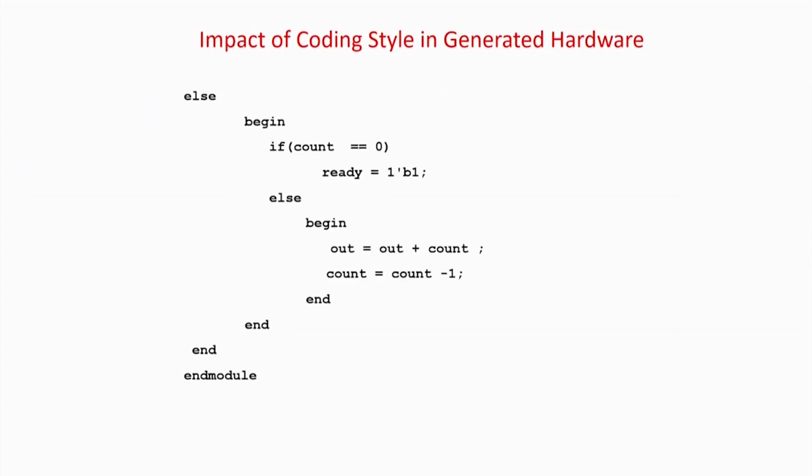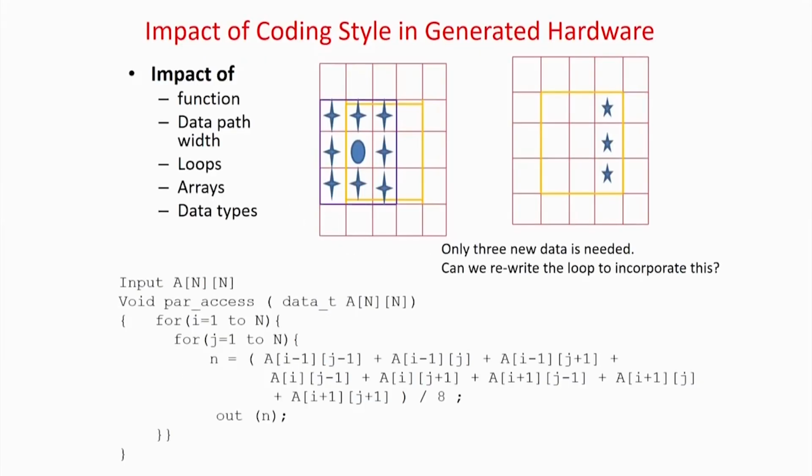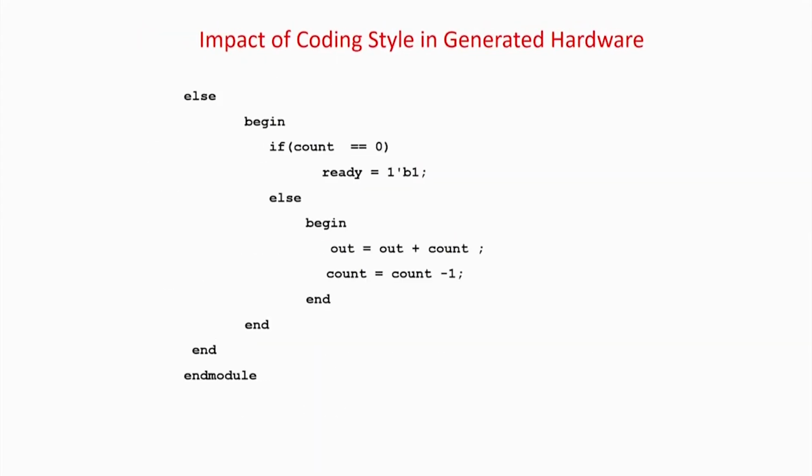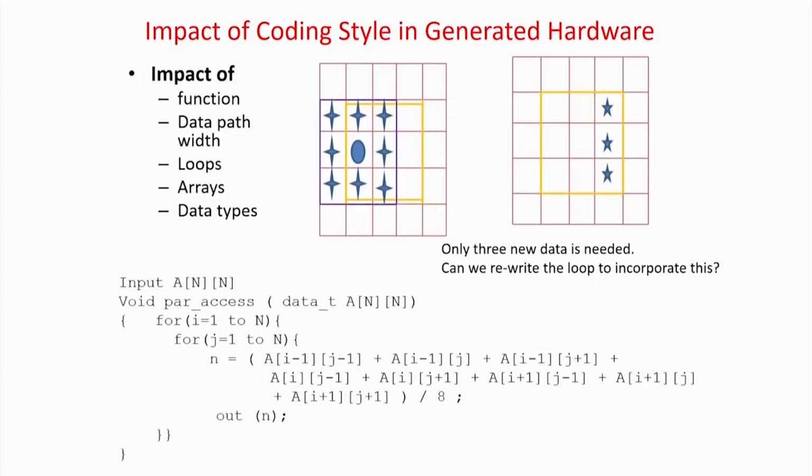This is just a very low level diagram for this hardware, and basically you can see that if you are using a counter, if count is equal to 0, this is a down counter. So basically here I am freezing it. This Verilog implementation will be cheaper because it checks count equal to 0 instead of n. If I go for n checking, this will be a larger circuit because count checking with n involves a lot of XOR gates, but count with 0 is a simple AND gate.